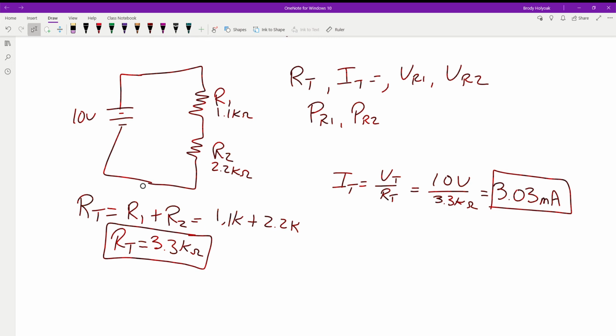The power supplies that you guys see in third semester have just the regular size wires. I think it's 20 or 22 gauge wire, and they're able to handle an amp or two of current. The stuff that you have in your houses, it's 12 gauge wire if it's 15 amp. It's 10 gauge wire if it's 20 amps. So the more current, the thicker the wire has to be to keep it from getting too hot.